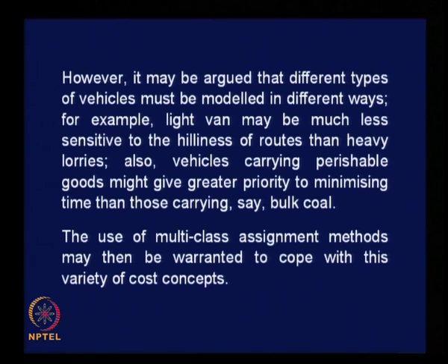What do you understand by multi-class assignment? Divide the goods vehicles into different classes based mainly on their size and speed, right, and do separate assignment for different categories of vehicles. For goods transportation, you may have to divide the goods vehicles into maybe 3 or 4 categories depending upon their size, to some extent the type of commodity being carried, and then assign each category of vehicle separately based on the requirement, and other sensitivities related to the operation of such vehicles.